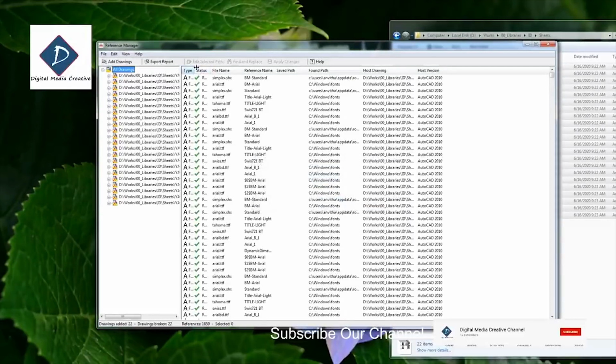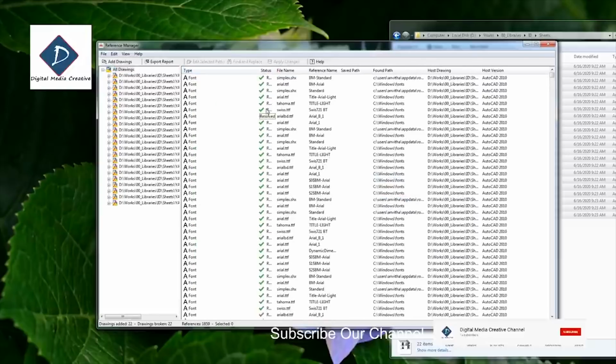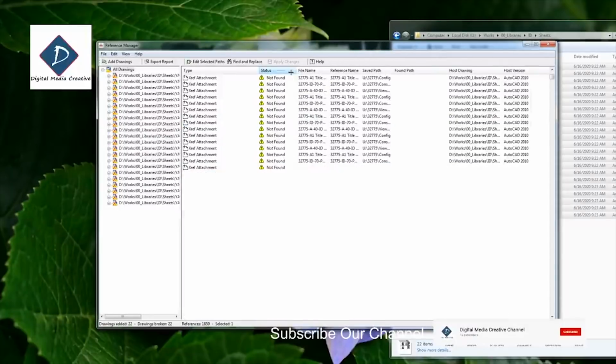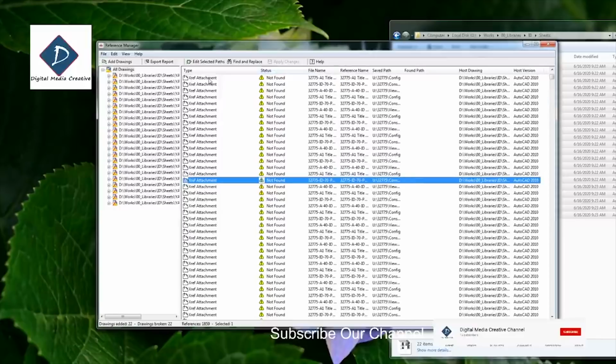So now you can see what are the things on these files. I'm just going to click on the type for the sorting. Then you can see, because we just need to fix the link only for the xref. Other things I'm not caring about. So you can see all these xref files.